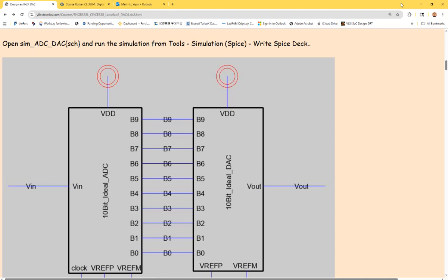Then all these 10-bit digital outputs are put into the digital analog converter. It's a DAC, which is the easier circuit. We're going to cover the circuit structure a little bit today and tomorrow. We're using the superposition theory for the calculation. The DAC is converting that digital signal back to analog. So you can imagine the output will be just one pin, but all these are 10-bit digital pins. It's just for simulation. You cannot find any applications for this.